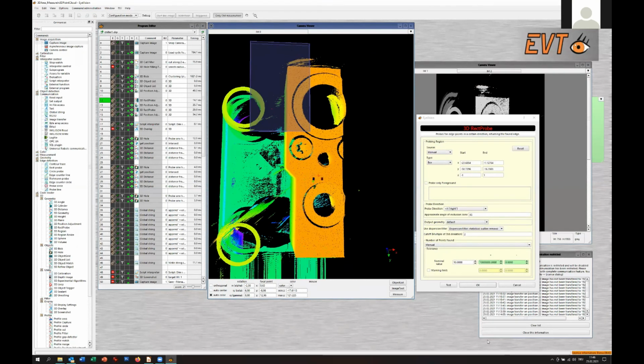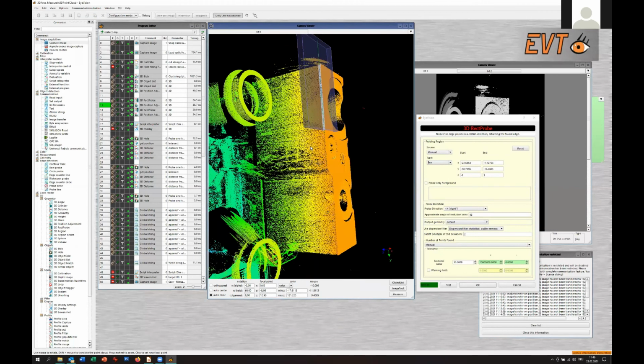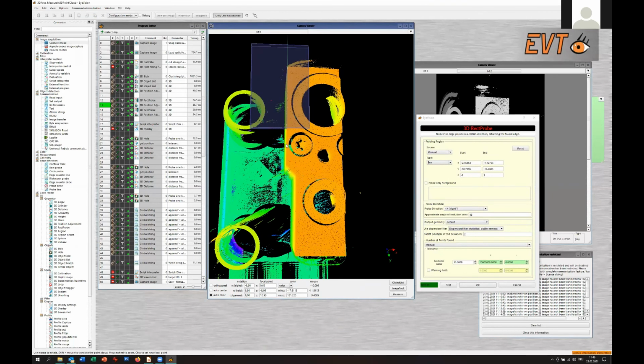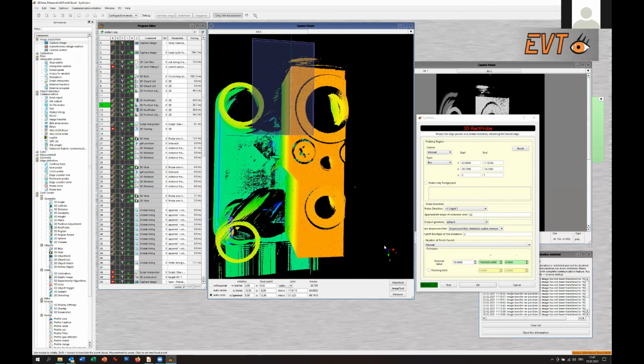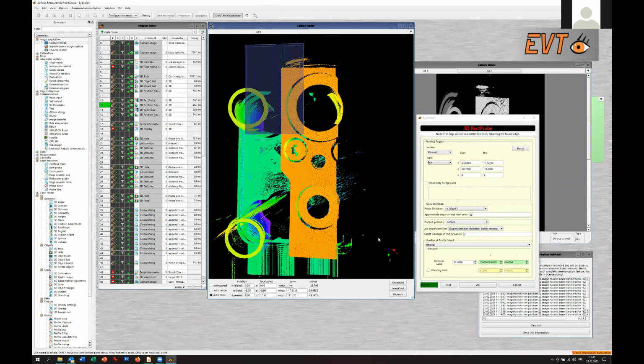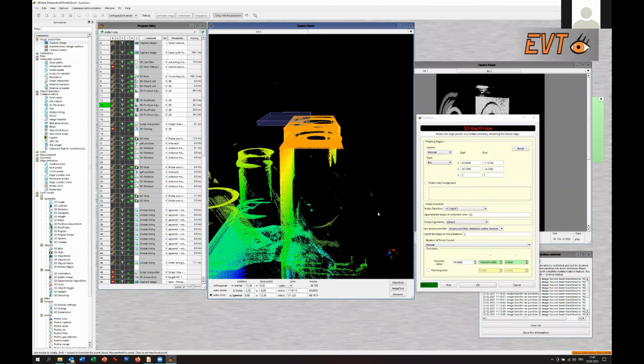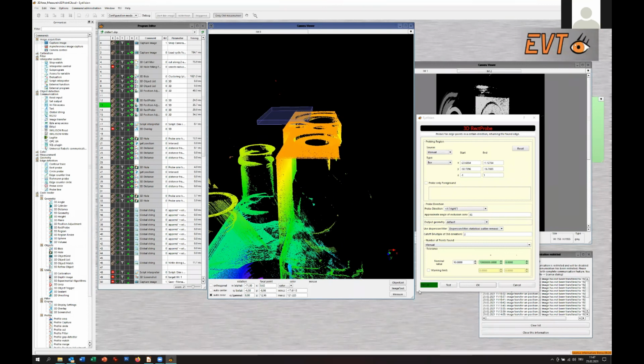Now if we press the test button, you see we measured this edge here. And if you look at the coordinate system, this is really one of the main errors one makes when suddenly working with 3D: you have to look in which direction. Now you see, of course, this is a positive Z.